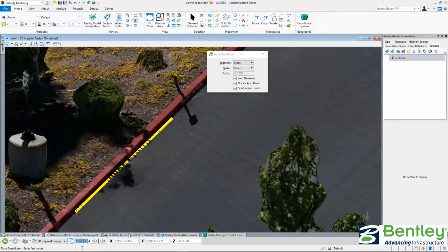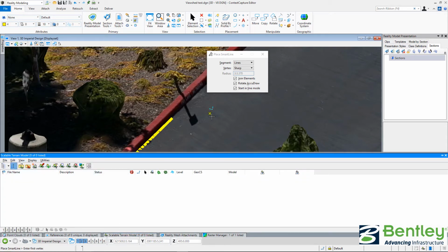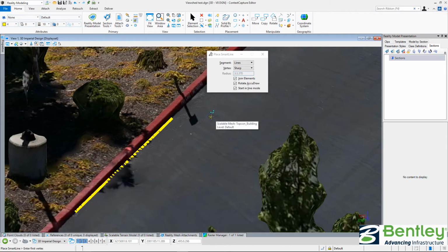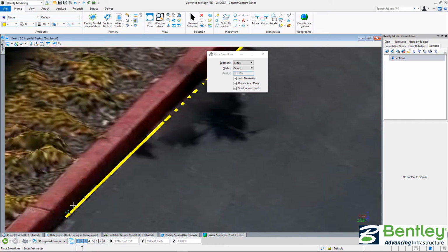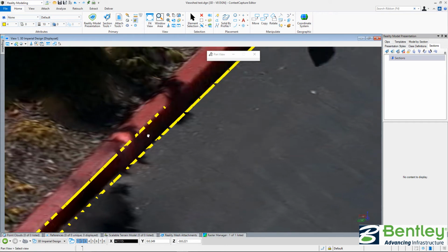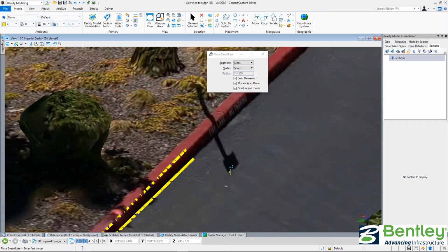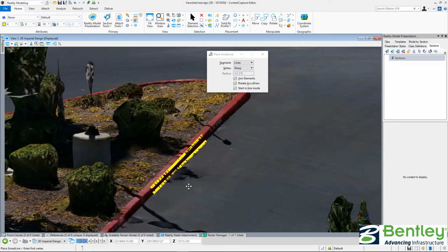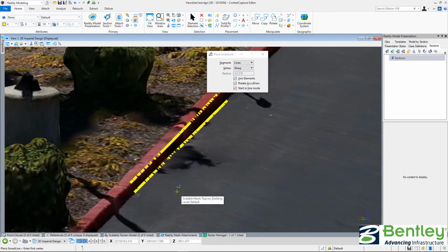Now these things in our scalable mesh, we can import them as break lines. So as we've seen in that previous file, I had a scalable mesh that created ground for me from bare earth, but it didn't have break lines at top and bottoms of curbs. This is where I would come in here and add top and bottom of curb. Now also the same way that we did the bottom, we can come in here and do the top. And I'm snapping directly to this mesh.